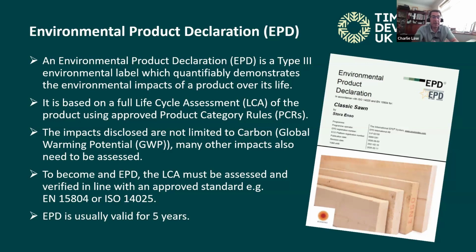Now, to become an EPD, that life cycle assessment is assessed and verified in line with the approved standard, and that's generally in Europe EN 15804, but if you've got international companies, that can be ISO 14025, and it's usually valid for around 5 years.